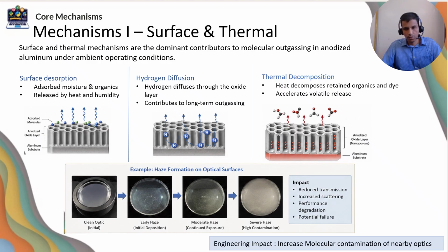And the next one is thermal decomposition. This is a little trickier than the other two mechanisms, where due to the temperature, there is a possibility that the dye in the seal, or the volatile elements, can decompose and outgas.